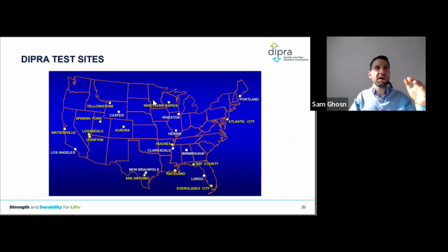You bury an iron pipe in Wisconsin where resistivity is 6,000 ohm centimeter, it will be there for 3 centuries, 300 years without corrosion control. So every environment is different, and if you have a failed pipe in your system, doesn't mean your neighbor in another city will have a failure as well, okay? So pipes age differently, and age is not an indication on condition of pipe. And that's the purpose of that webinar, actually.